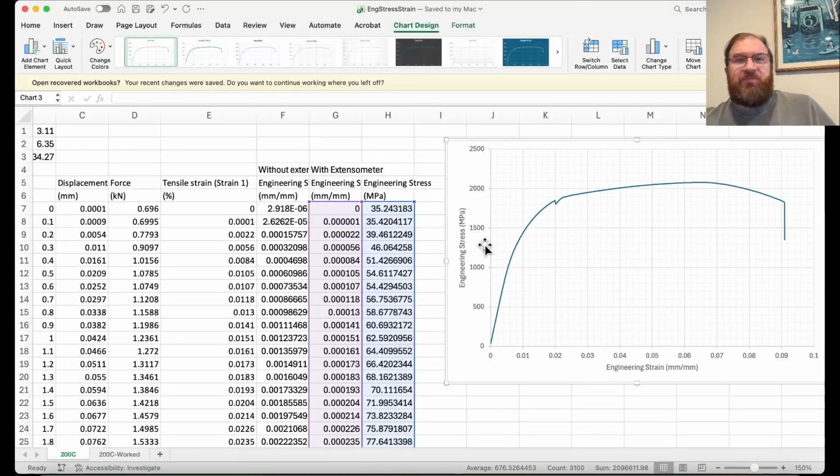So we're back here, and I want to go through how to calculate the elastic modulus. And if you'll recall, the elastic modulus was the slope of the linear elastic portion. And for this particular graph, you might notice that it actually has a pretty good gradual transition region, right? It looks like it actually starts to gradually transition through a whole host of things. And so because of that, we're going to probably focus on some of the early curve to be able to get our linear fit.